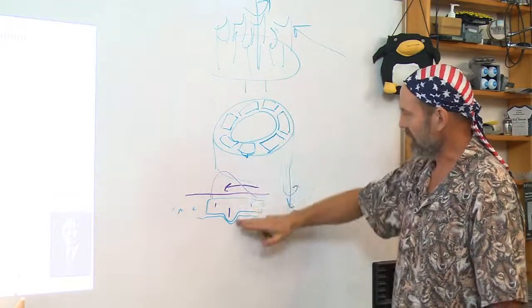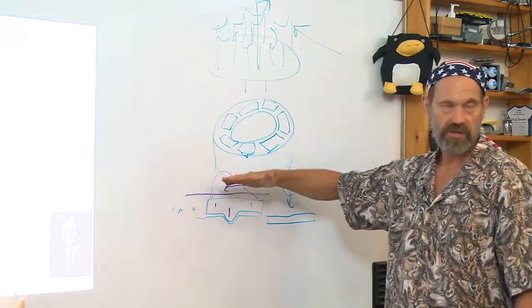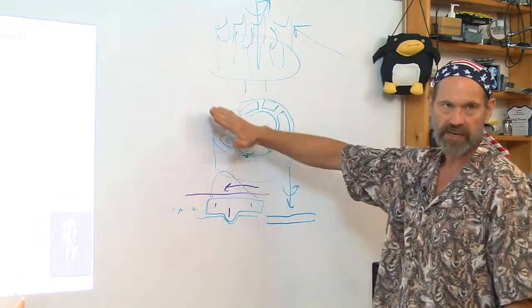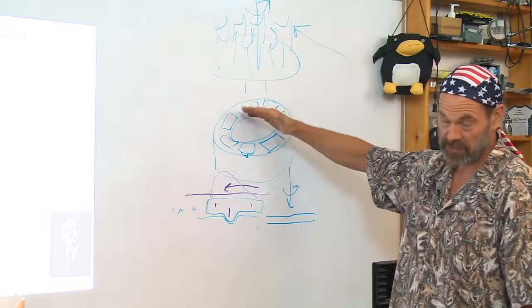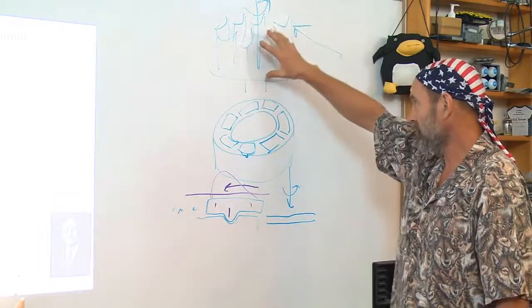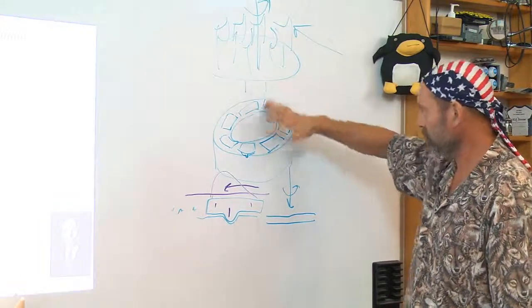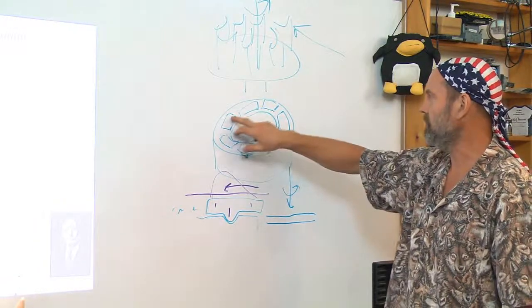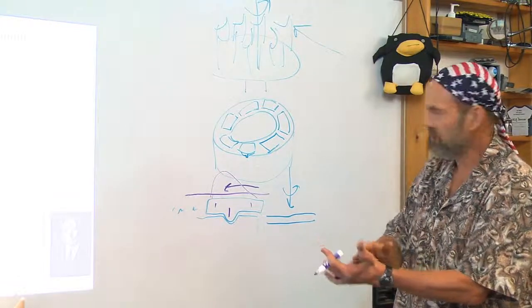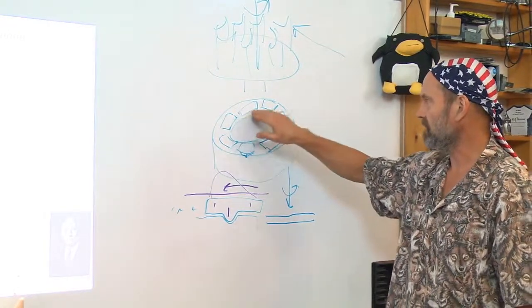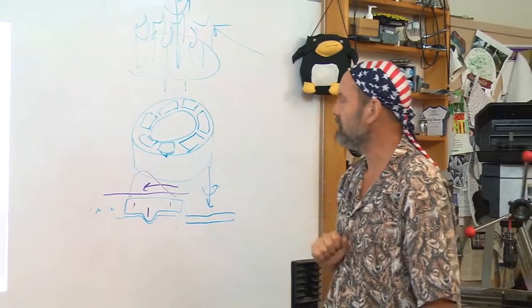They just have to have a common plane on their entire top surface when there is just a static load and no lubrication. Put the turbine impeller down here, push, and it should touch all of them. And remember we talked earlier about rubbing a bearing, so that's how you could tell that they're all at the same height, by rubbing a bearing and scraping them as appropriate.